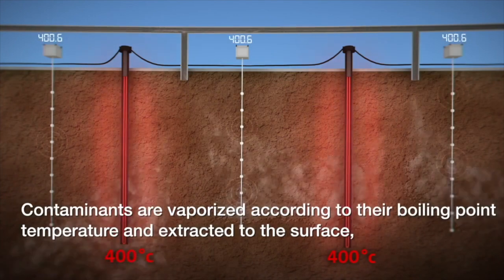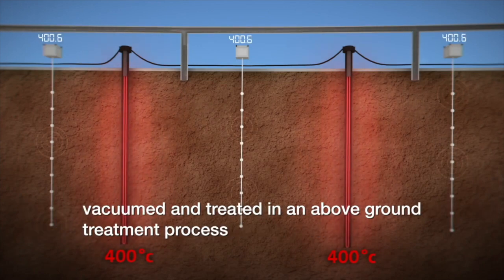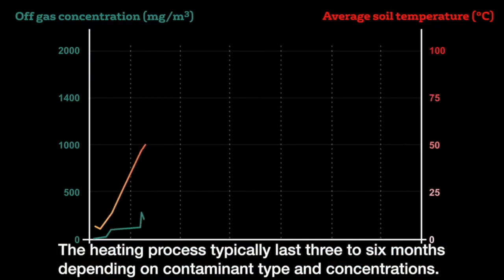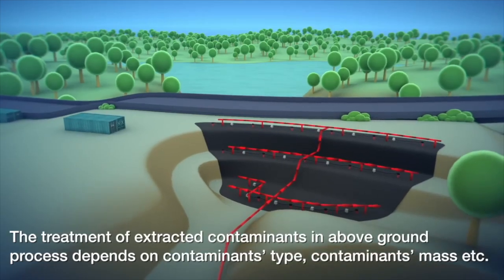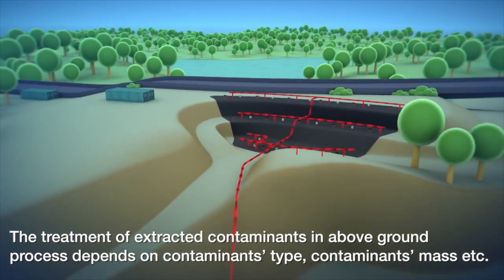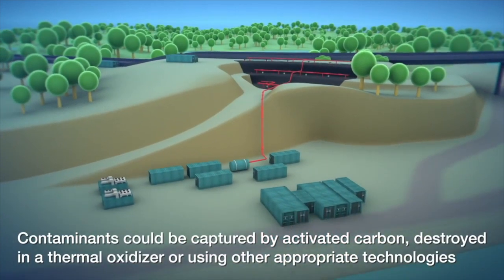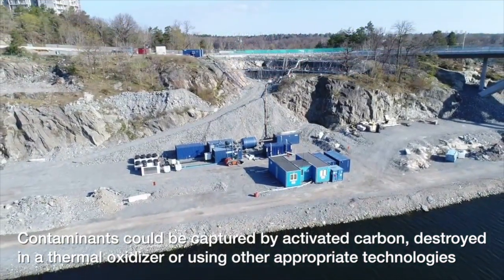Contaminants are vaporized according to their boiling point temperature and extracted to the surface, vacuumed and treated in an above-ground treatment process. The heating process typically lasts 3 to 6 months, depending on contaminant type and concentrations. At the end, almost 100% of the contaminants are removed by electrical thermal conductive heating technology. The treatment of extracted contaminants in above-ground process depends on contaminants type, contaminants mass, etc. Contaminants could be captured by activated carbon, destroyed in a thermal oxidizer, or using other appropriate technologies.